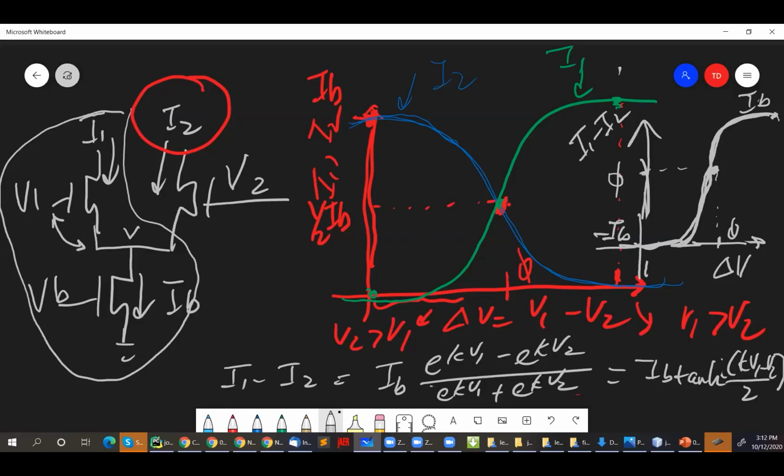I'm just curious whether you know why I can even consider this circuit to be in subthreshold and what makes it subthreshold. Because we're not talking about a single transistor, we're talking about a set of transistors. Okay, Vincent says VB. Jeff says VB. Yeah, that's correct. Because in the end, the current that flows through the circuit is dependent on VB. VB sets IB, and the two other currents that flow through the remaining two transistors have to sum up to IB. So this voltage sets whether the whole circuit is in subthreshold or not.